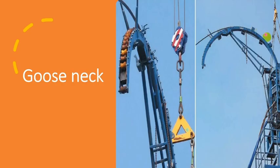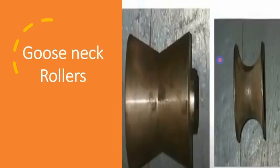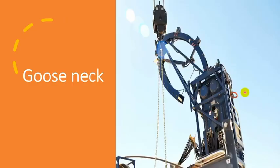It goes around the gooseneck, so it is bent to a specific diameter so bending stresses are not high. Also, it moves around rollers. As you see, these are rollers that reduce stresses and friction between the gooseneck and the coil tube.